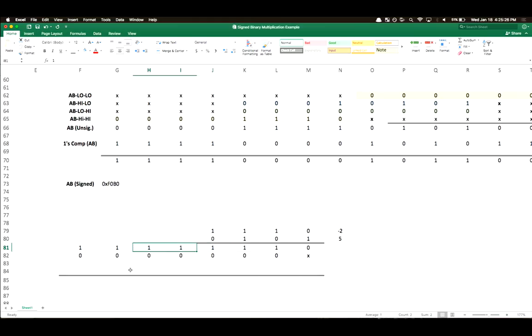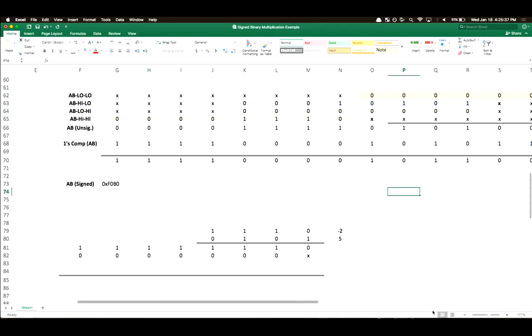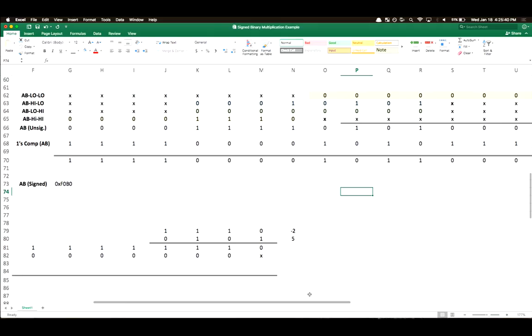How does that affect it when you need to reset? For this part? If you're splitting it up this way, you have to add certain parts of your 4 8-bit results. So in your case, if you do it this way, for problem 17, you're going to have 4 16-bit results, and you need to find a way to make that one 32-bit number that's the correct value. But since you split it up into 4 pieces, you have to add certain parts to it to get that correct result.